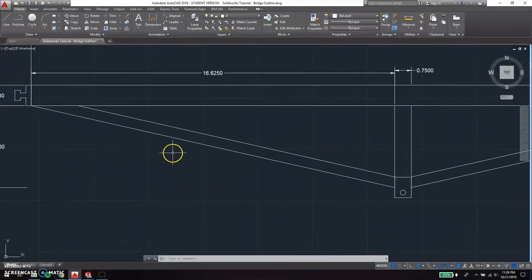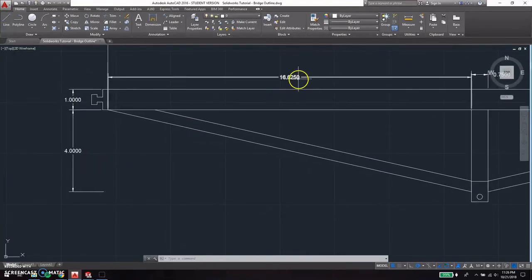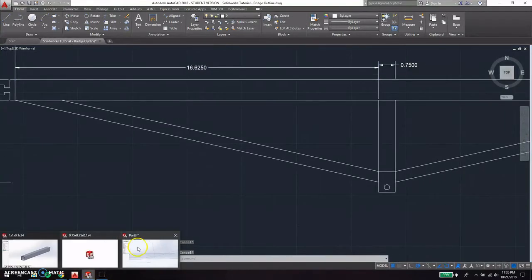So as you can see, the dimensions that we used to measure our piece are basically the dimensions that lay out this line right here, which means that we have to make sure that the rectangle we're going to use to extrude this piece is aligned right here. It has to be perpendicular here and then extruded in order to achieve this. If you have it anywhere else, you're not following these dimensions, this dimension here and this dimension here. So let's go back and fix that up.